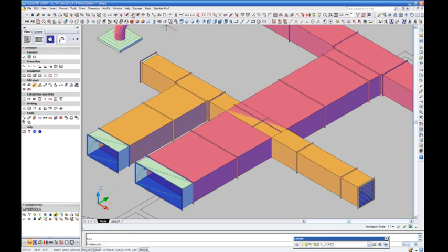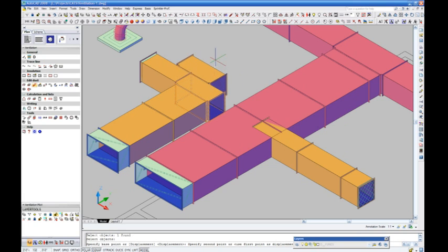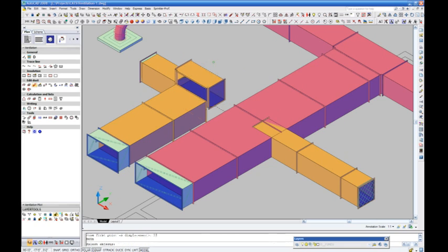We will now redesign our return duct at the collision point. We will eliminate the duct section to the right and raise our T 12 inches in the Z direction. We will eliminate the duct toward the fire damper.